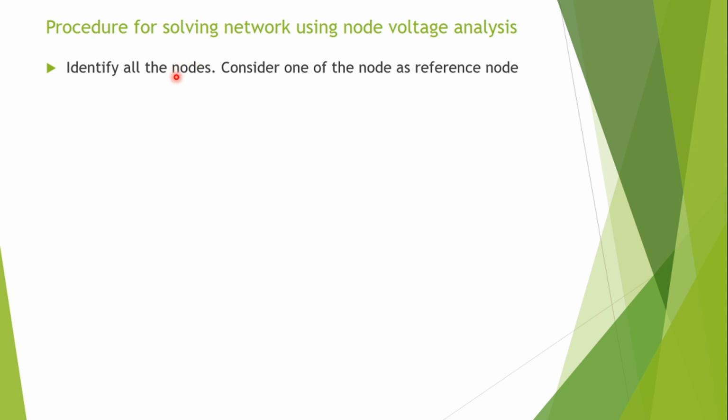So first step, we need to identify all such possible nodes, and among those, any one of the nodes as a reference node. Any one node, but you can give a preference that the node with the maximum elements connected you can consider as the reference node.